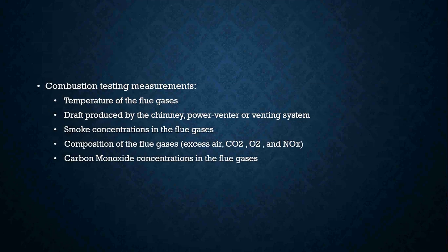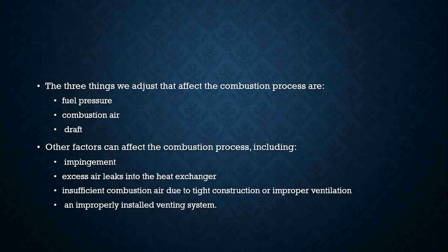Okay, combustion testing measurements are definitely temperatures of the flue gases, and draft produced by the chimney, whether that's power vented or just a simple standard venting system. You are going to measure your smoke concentrations in the flue gases. You are going to measure the composition of the flue gases: how much excess air you have, how much CO2, how much O2, and how much NOx you are going to be emitting. You are also measuring carbon monoxide concentrations in the flue gases.